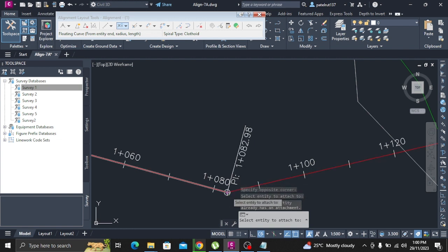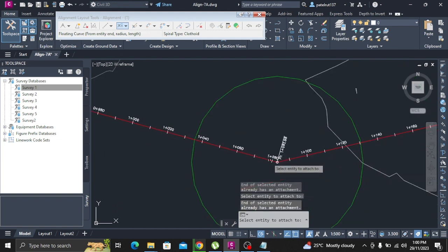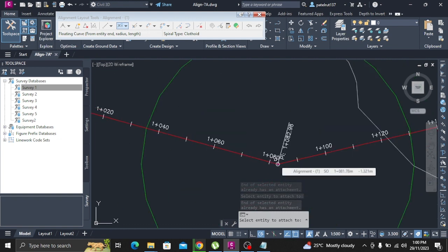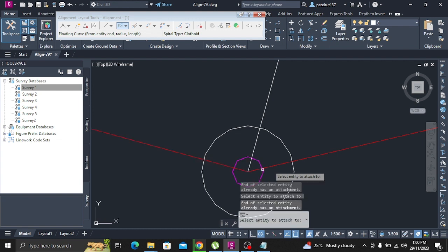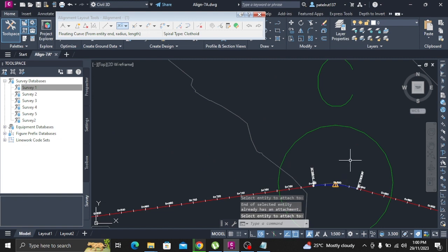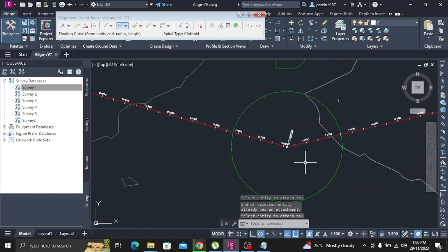In the Design Criteria File Editor dialog box, on the left-hand side, ensure that the Local Standards Emax 7% table is selected. On the right-hand side of the dialog box, select the first row in the table. Click the Speed cell. Select 50 from the list. Click the Radius cell. Enter 54. Press Enter. Repeat steps 2 and 3 to add the following values to the table.